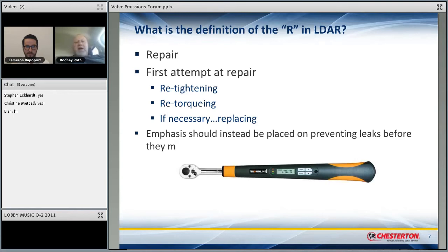And then that valve is tagged as a leaker, and then it has to monitor 2 consecutive months below the threshold required before that tag can be removed. And then if it doesn't, then it becomes a chronic leaker, and it goes on a totally different list, and then the fines start to occur.